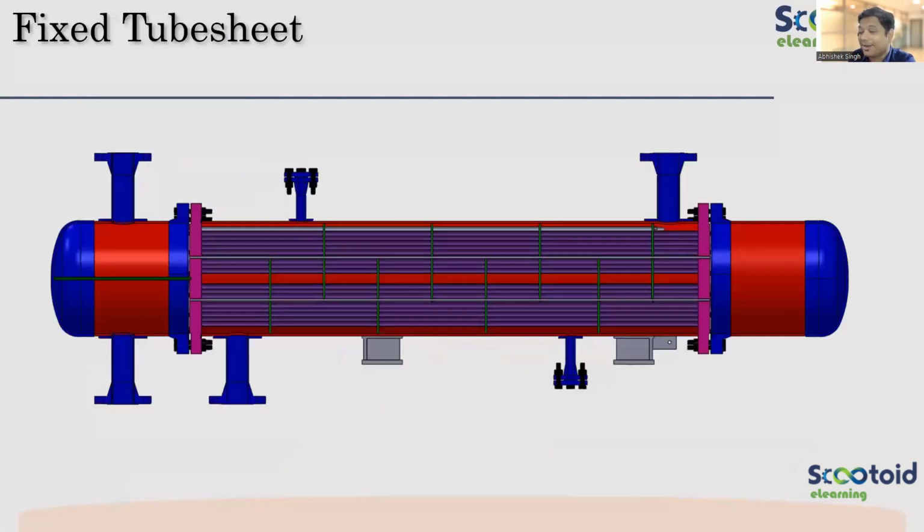Now, come on, name this. See who is first. What is the nomenclature for this heat exchanger? Harsh, BEB? There is no B type in the rear end, Harsh. You remember the opposite of B? Omkar got it first, and absolutely right. It's BEM. It's not a U tube, right? Somebody has said U type also. There are no U tubes, so it cannot be U type.